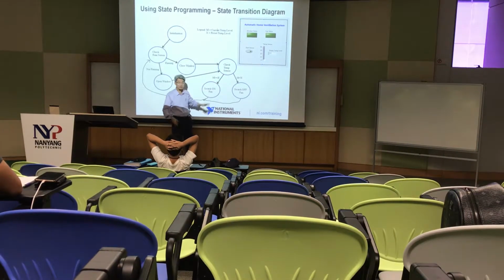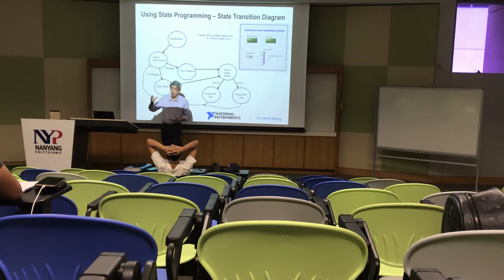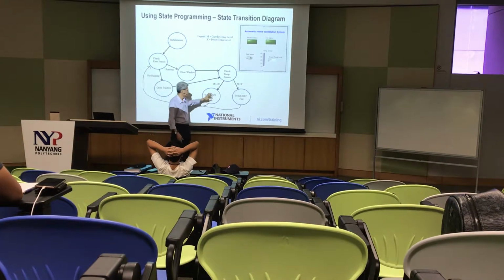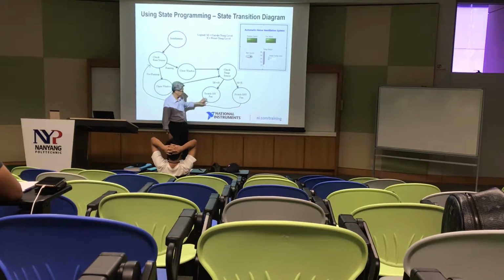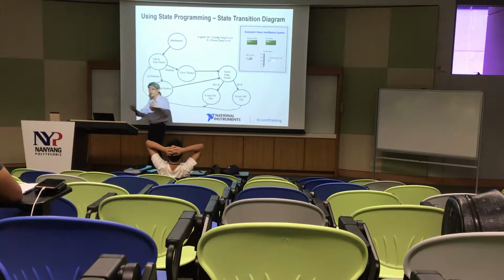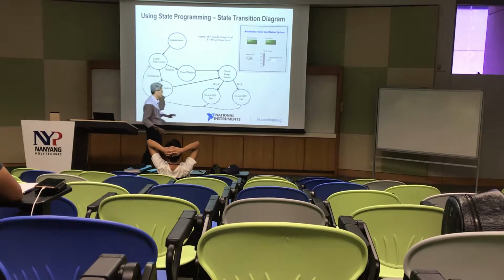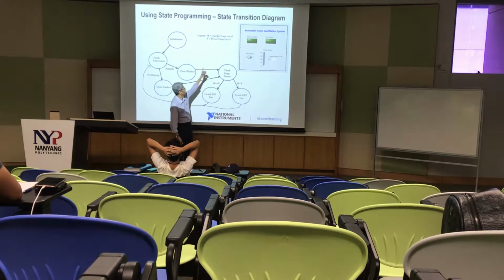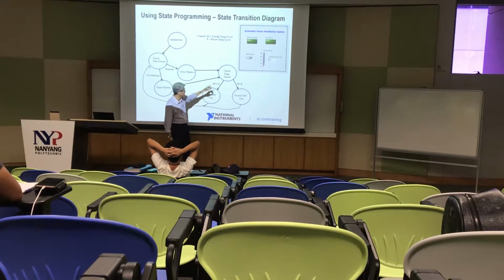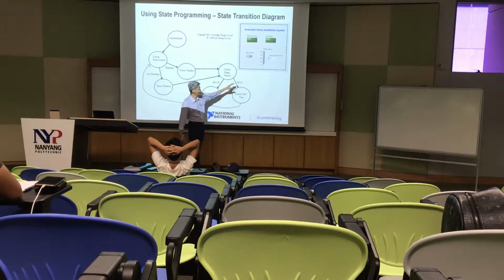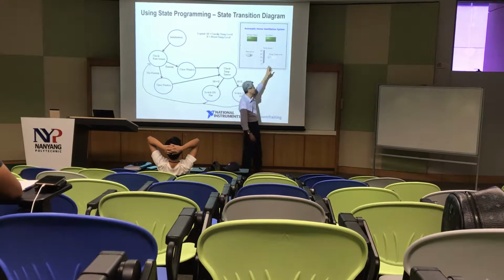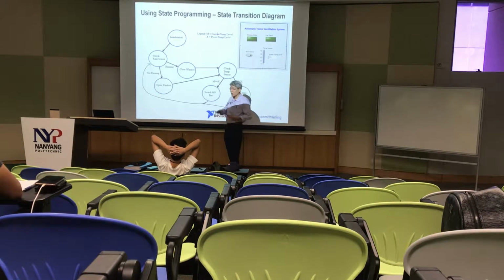So, if the house is getting a bit hot, you can do something. Do what? Switch on the fan to ventilate. Okay? So, it compares M, the current temperature of the room, with X, the preset temperature. You preset it to whatever temperature you want.